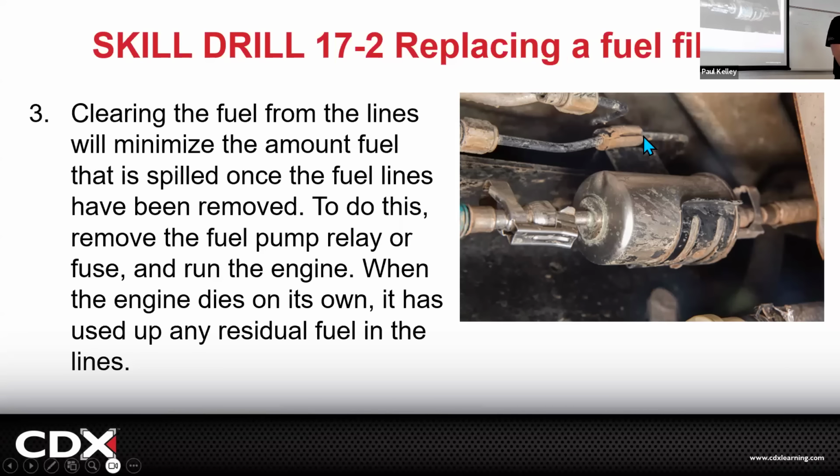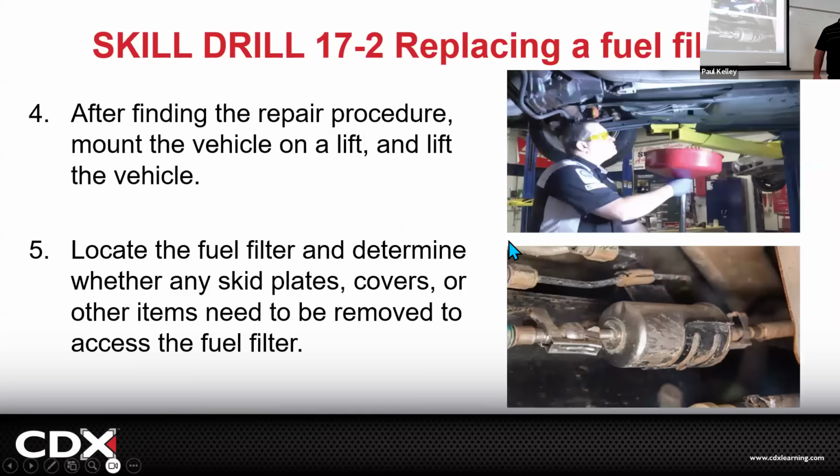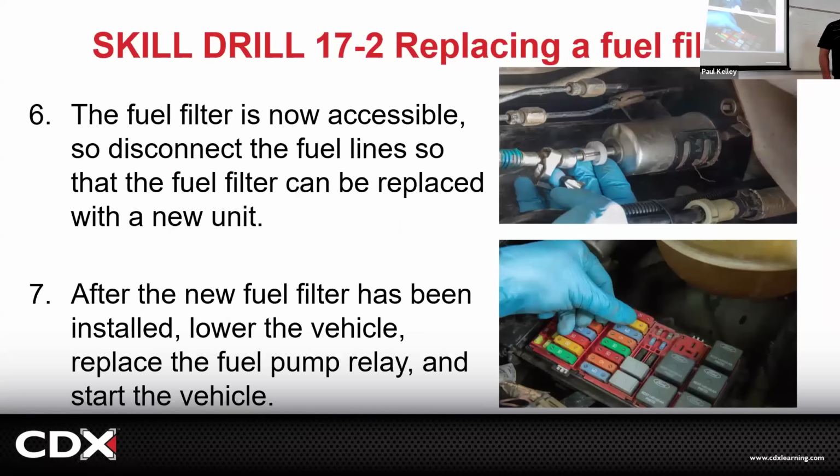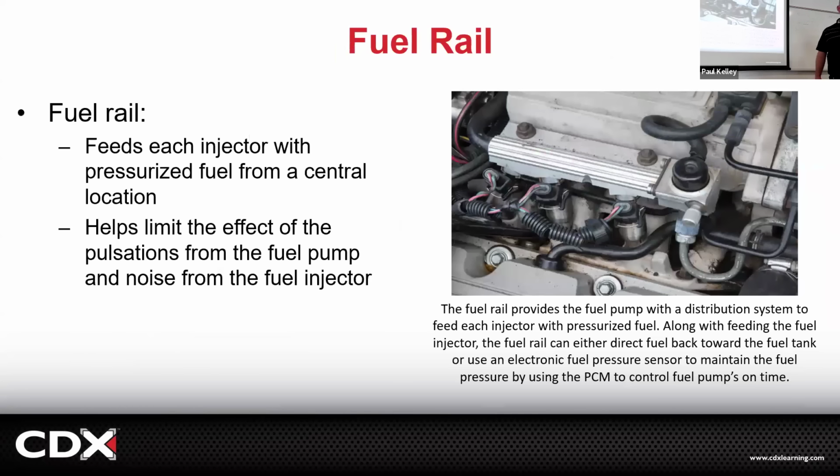But this may actually need a special fuel line release tool. Sounds kind of a hassle. Put the drain bucket down. Sometimes we'll even disable the fuel pump, but I don't really see any particular reason. I'm just popping it off there. I'm going to let it drain. I'm going to try to do it fast. Not a real big deal.